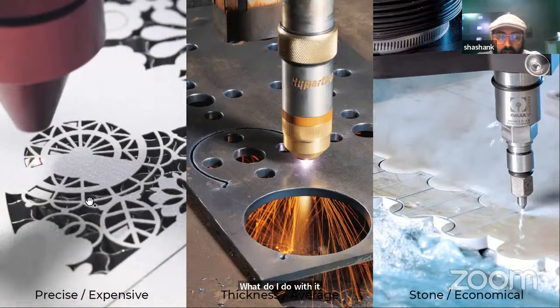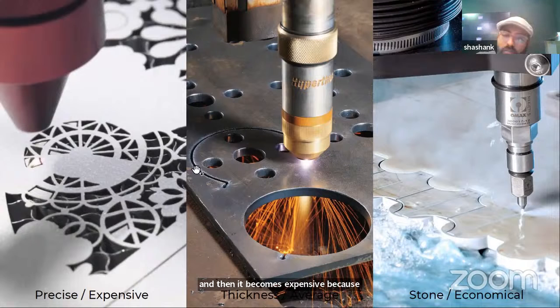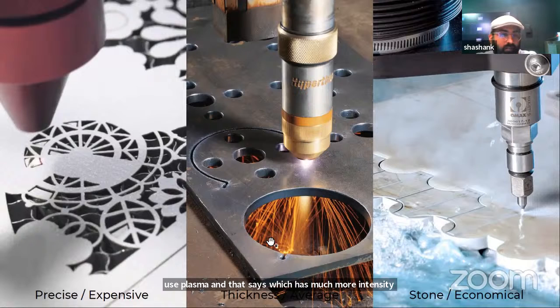Laser can cut about 15 mm of thickness of a material, but you have to run it at a higher setting. More electricity goes into it, and then it becomes expensive because it starts cutting much slower. So it's easier to use plasma in that sense, which has much more intensity for cutting much thicker material. In the image you can see it's much thicker material. Anything above 15 mm becomes easier, or let's say 10 mm for an easy calculation.